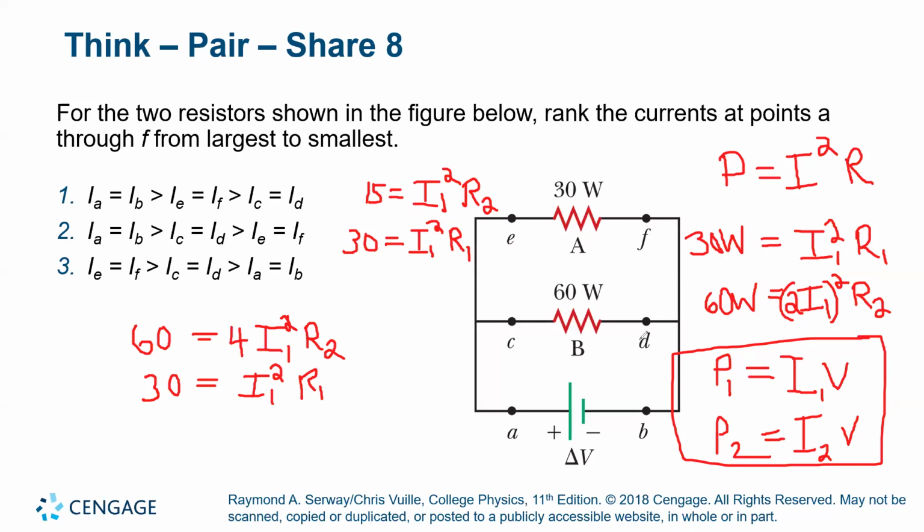So we solved the problem here, and let's talk about it. Okay, we're almost done solving it. We have one step left. So we understand that the currents have to have the 2-to-1 ratio because we see Joule's law is pretty simple here with the I and the V. And we're going to now rewrite the power equation using the resistance R1 and R2, which is actually the A resistor and the B resistor.